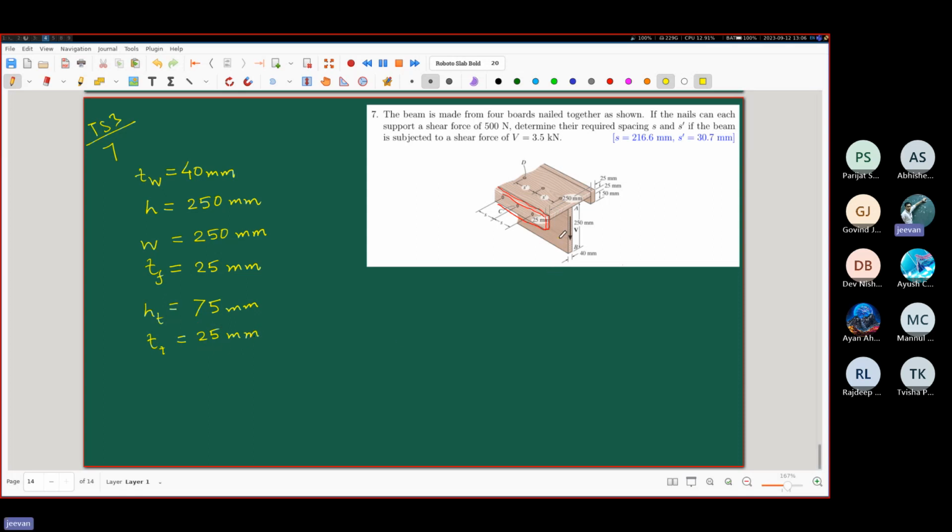Now suppose I consider just this little bit, then for that, Q will be how much? Suppose for the calculation of the Y bar, I have started from the top edge, because most of the things, all these complicated little joinings, are near the top edge. Suppose my reference is that top edge, so Y bar is calculated with reference to the top edge.